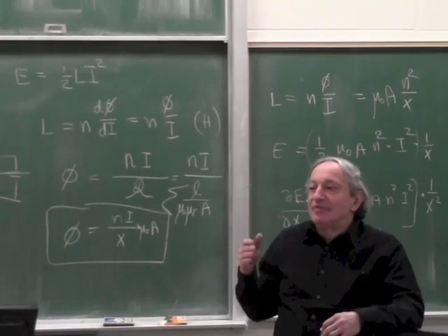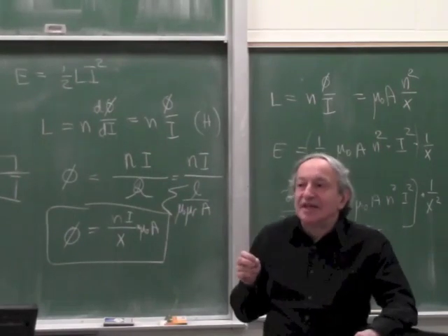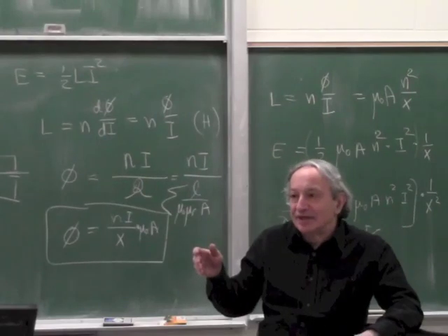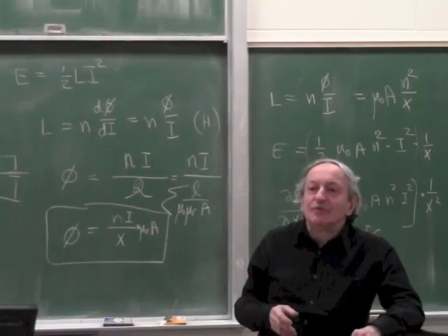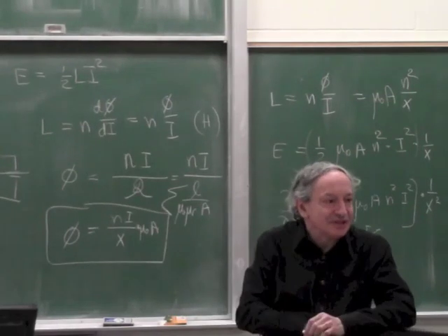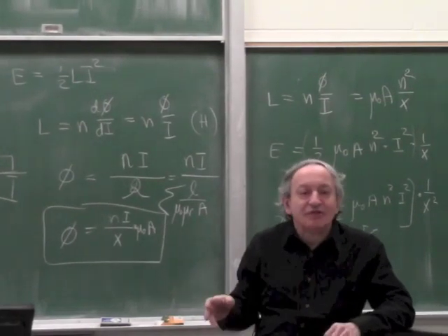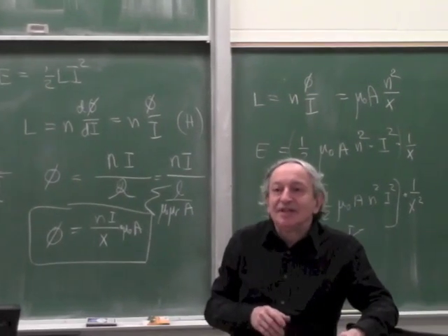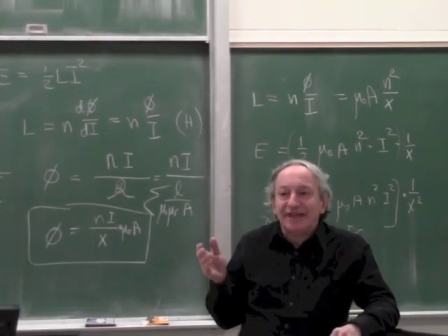You have to make sure that at the highest gain, the phase shift is less than 180 degrees if the gain is more than 1, right? So basically the worst case for stability is when it's almost closed, where the gain is highest. You have to make sure there's no phase shift, you have to put some special limitations on the servo, but then at any other position it lacks gain.